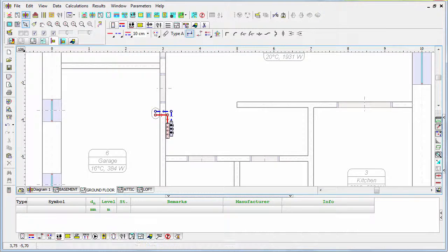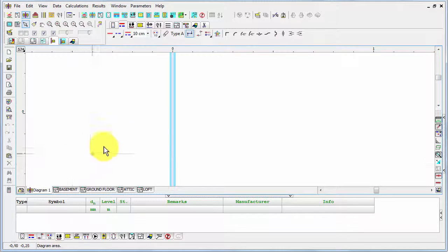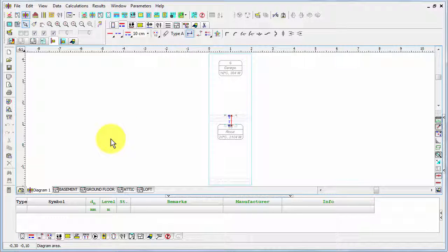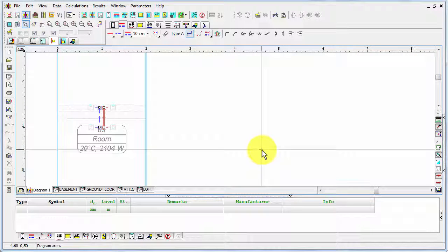And we can also go to the Diagram tab. And now let's press Ctrl R, and you see that automatically a simple diagram was created, and you may see these automatically created risers also in the diagram. They are very short in this example, but still these are the risers.